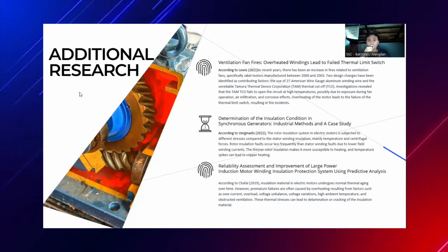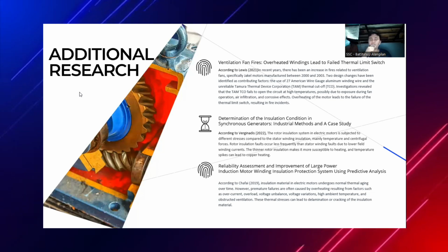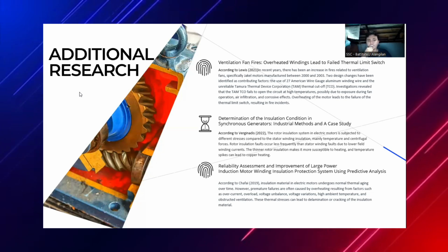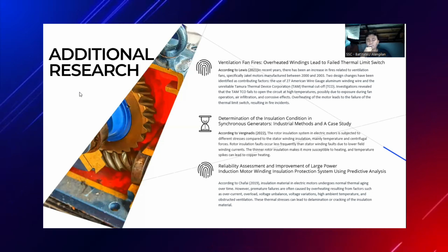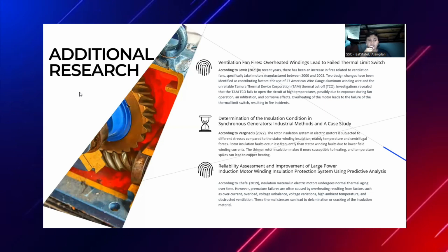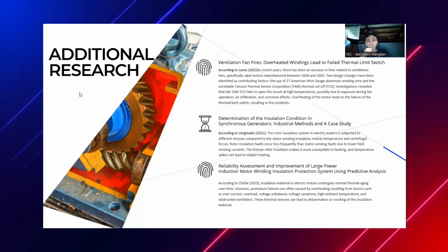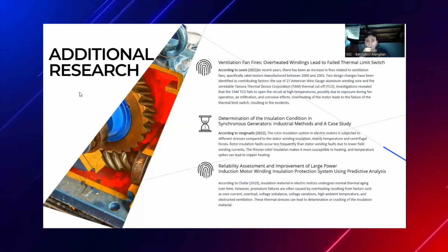So, based on this statement from this case study, we can conclude that the windings in the rotor are so thin that a sudden increase in heat can lead to copper heating and can melt or deteriorate the insulation winding inside the armature slots of the rotor.